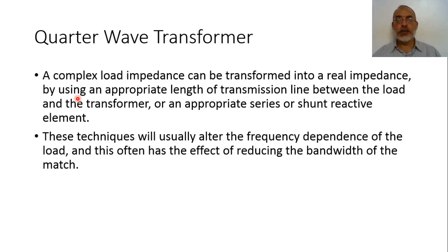The question is, what will happen along a certain bandwidth? Along a certain bandwidth, this shunt stub or series stub will not have the exact susceptance or reactance which has been designed at the center frequency.